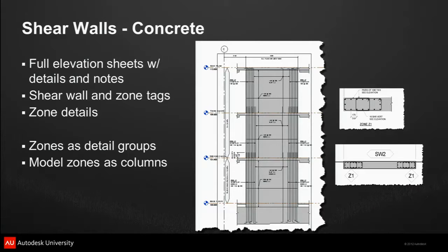Then you went to modeling the zones as columns. That worked really well. I've got the columns filtered out of the schedules and out of the views for their surface edges, and it works great. Hit the extensions, model up the reinforcing. I can tag it in plan every time I change the elevation, or if they cut an elevation in a different method. The zones don't get confused. You know which way they are. It's all linked parametrically. I was in the process of changing this actually to assemblies before I left.